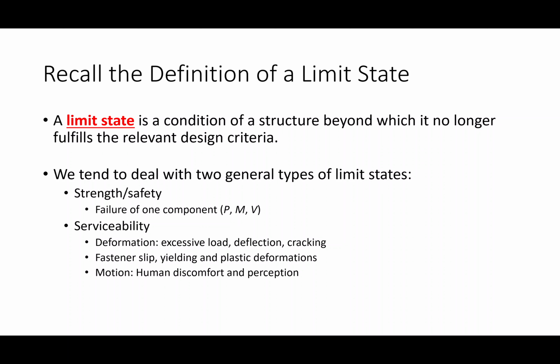Because if you're on a floor and it's moving up and down, that's not very comfortable for you as a user, right? So if you are in a situation where vibrations are something to consider, you might need to change the design of your structure, not for strength, but more for human comfort, human perception, and things like that, okay?